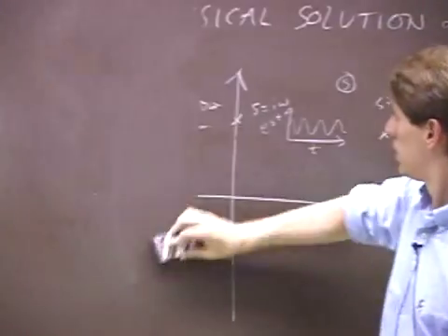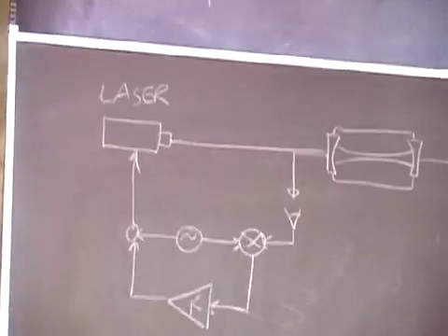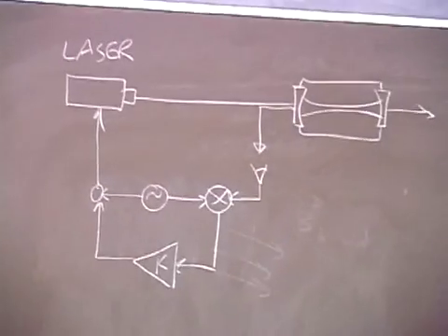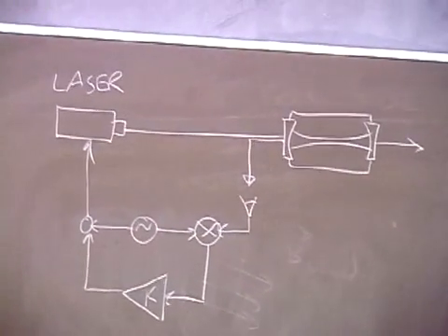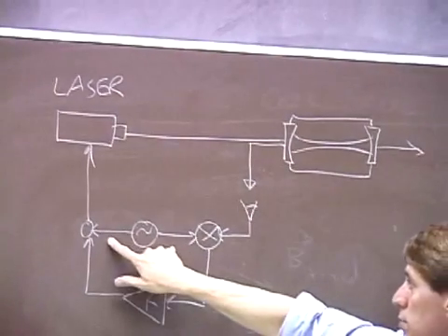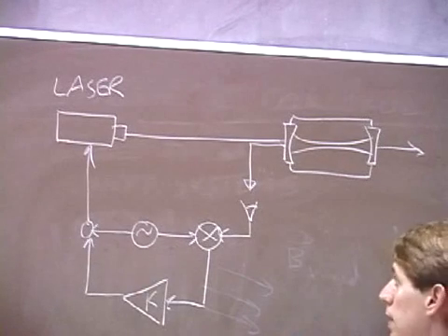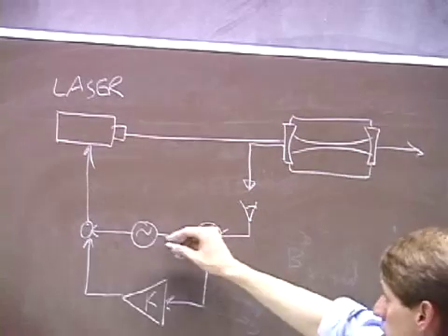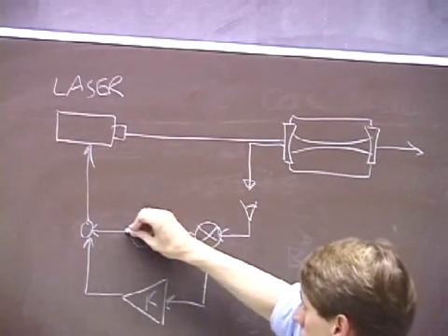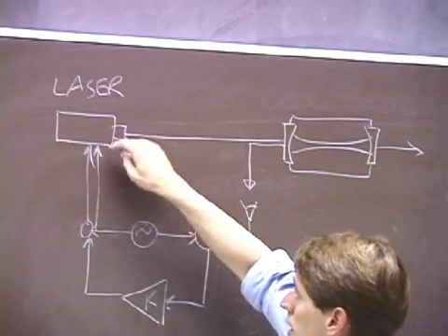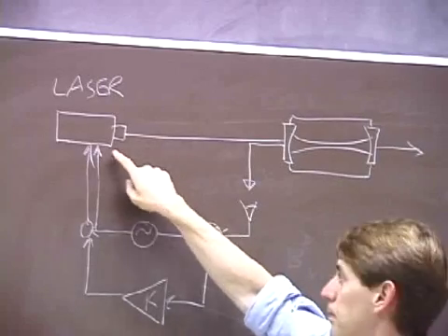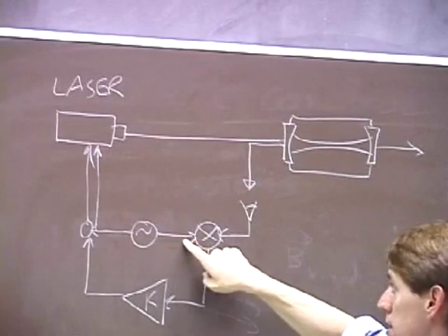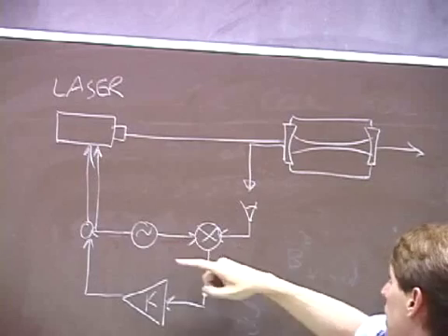Can we just understand the diagram? Yeah, a little bit more. Sure. So your oscillating voltage puts out the same signal in both directions. That's right. It puts out the same signal in both directions. And then just trace where each signal goes. Okay, so this is the oscillating signal. The oscillating signal goes in here and modulates the laser frequency. Another copy of the oscillating signal goes into the mixer.